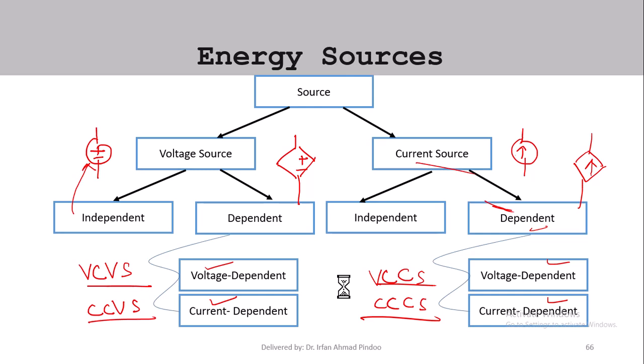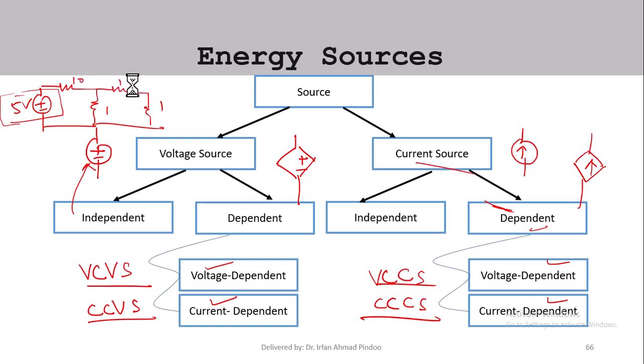Now what is an independent source, what is a dependent source? Let us understand that also. Suppose we talk about a system where we have a battery and we have some circuit, like this. Now suppose this value is 5 volt. It means that all the time this battery is capable of delivering this 5 volt irrespective of the value of the resistors. If you keep on changing these values, will this affect the battery value? The answer is no, because it is a constant. So they are independent. Same is the story of the current source also, which is independent.